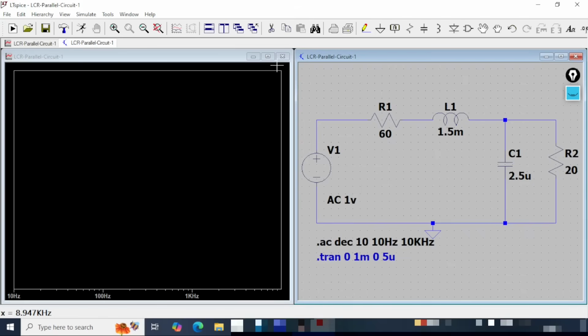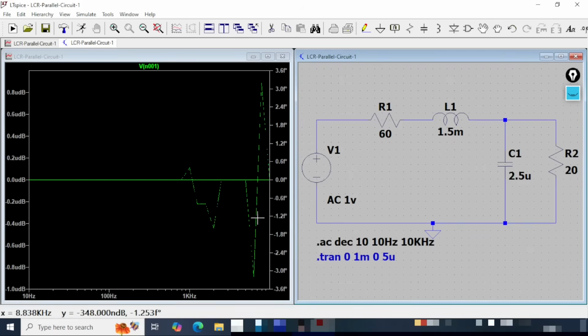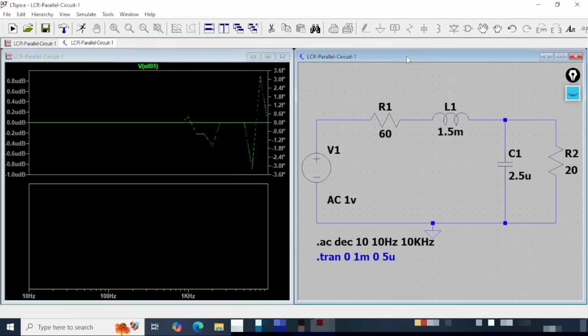Our circuit is already checked in the last analysis, that is the transient analysis. I'm not going in that direction. So I'll come here. First, I'll click here, hold, drag this. Okay. So this is a flat AC voltage. Okay. So let me hit B from the keyboard to make room for the others. Now I will click on the resistor, hold, drag and release.